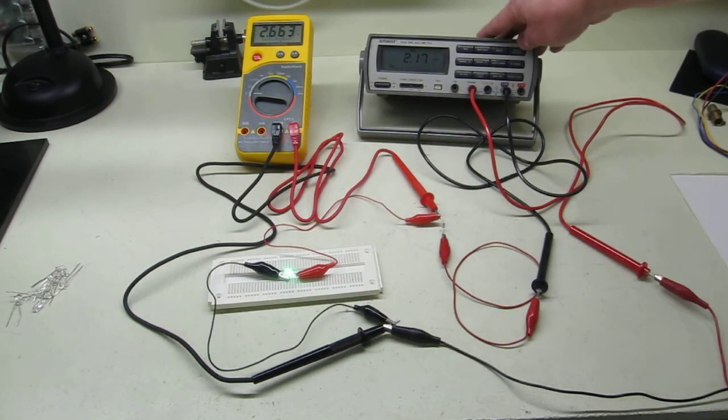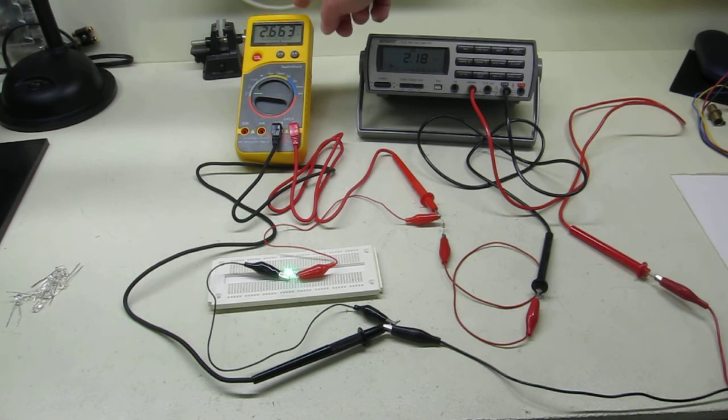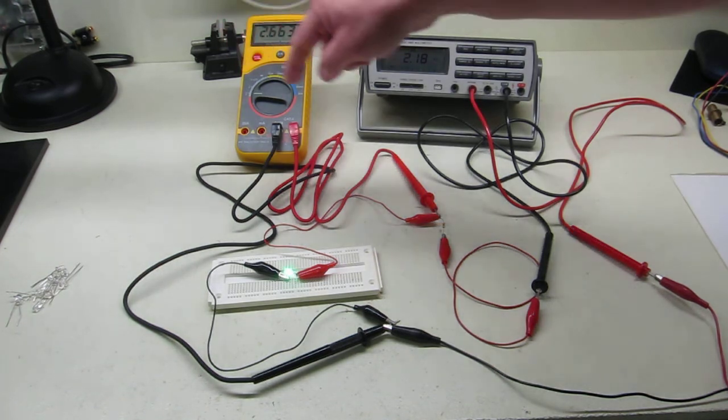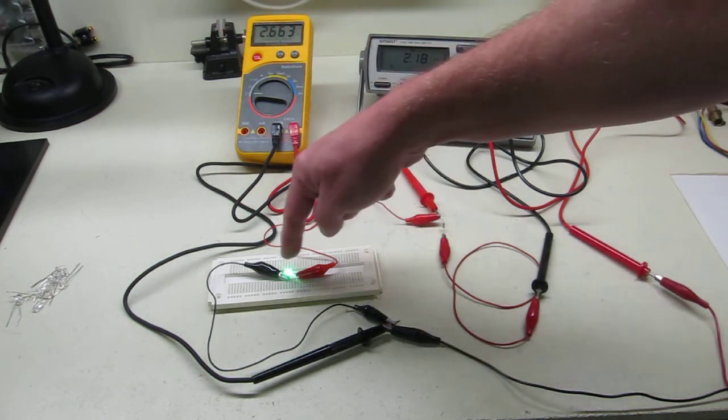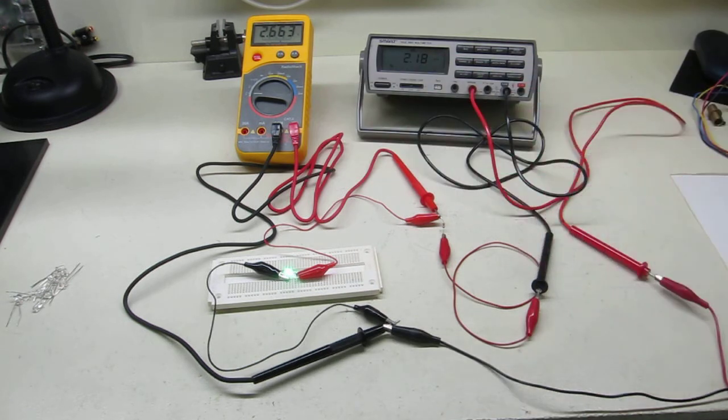This meter measures current, therefore. This meter is a voltmeter, and it's located directly across the terminals of the actual LED itself. It displays the voltage across the LED device, but not necessarily right across the junction, since there's electrical losses within the semiconductor itself.